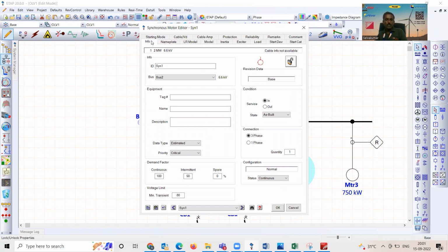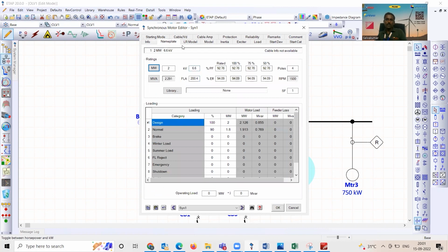But giving unity power factor slightly stresses your excitation system more, and temperatures rise, because you need higher field current. Instead, if you set 0.98 power factor lag, this has an advantage that it will not draw any reactive power from the source.